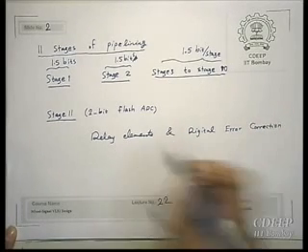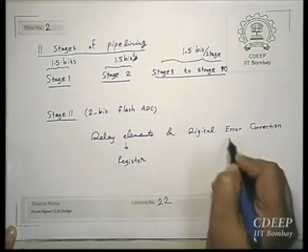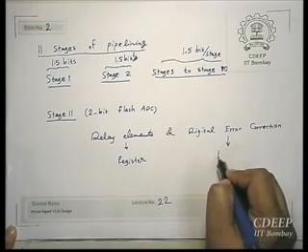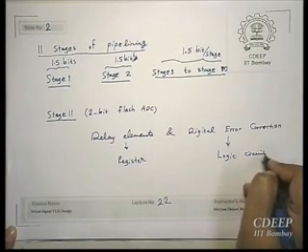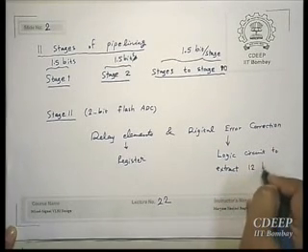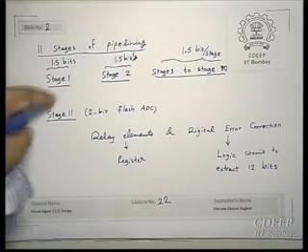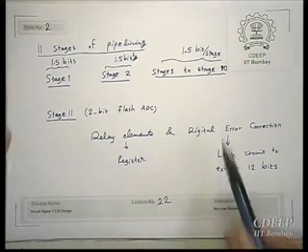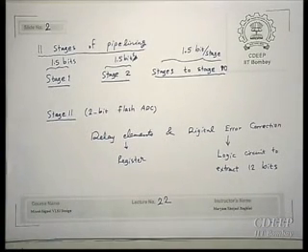Actually this delay element is the same as a register, and this digital error correction is that logic circuit to extract 12 bits. Because you will have 2 bits at every stage. You have 10 stages, it's 20, and then plus 2 bits at the end. But you will extract this 10 out of 20, plus 2 will be 12 bits.